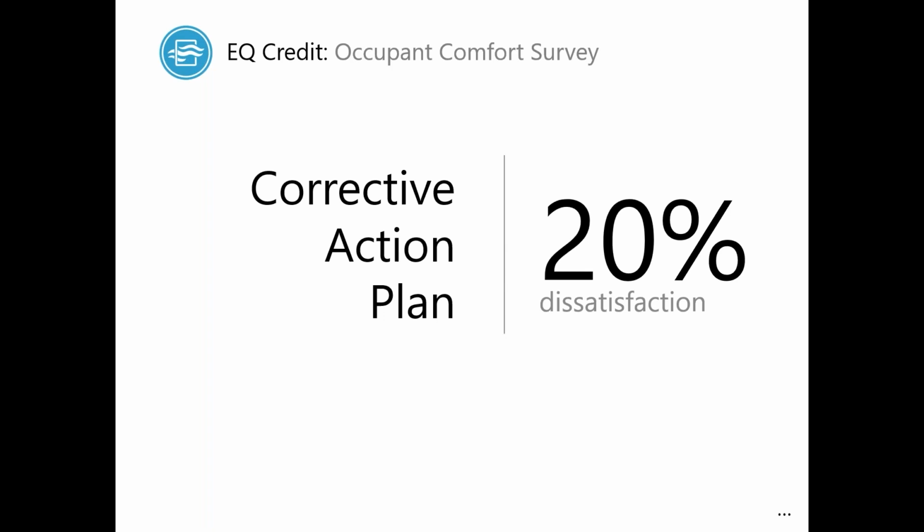So this is a good idea and a good area where we can identify, are there areas in the building that maybe people are really uncomfortable? Maybe we can find some themes. If an entire facade of the building, everyone on that side of the building is hot, maybe we have some HVAC or set point issues that we need to deal with. If everyone's cold on one floor of a building, maybe that shows that we need to do a little bit more investigation.